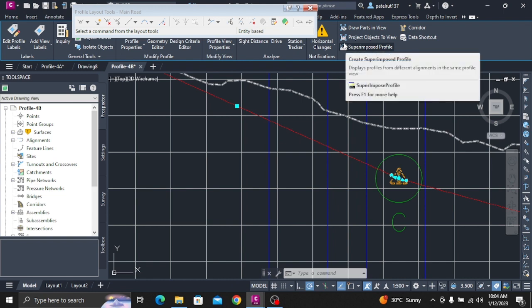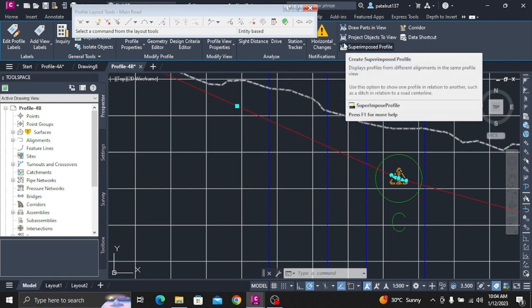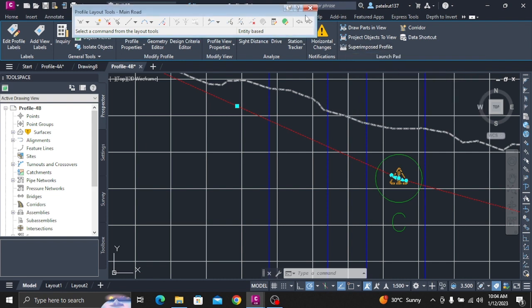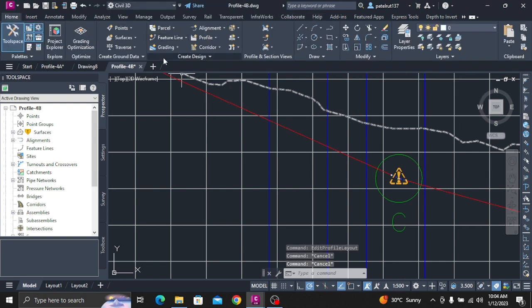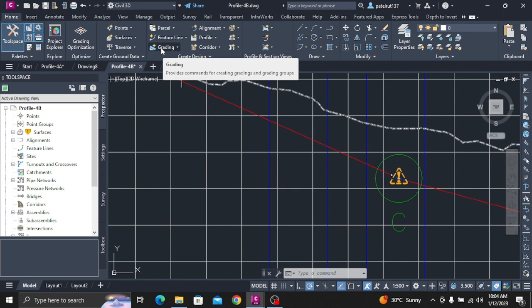Click Apply. Under Grid Options, select Clip Vertical Grid and Clip Horizontal Grid. Under both selections, select Omit Grid in padding areas. Notice that the graphics in the dialog box change to demonstrate the effect the setting has on the profile view. Click Apply. The grid is clipped to the surface profile because the clip grid setting in the profile view properties for PV1 is set to the centerline surface profile. Setting the profile view style to clip to highest profiles would override the property setting and clip the grid to the layout profile. Click OK.